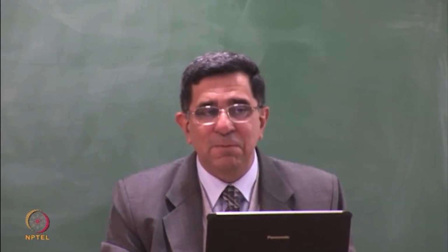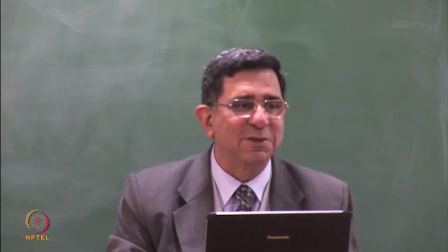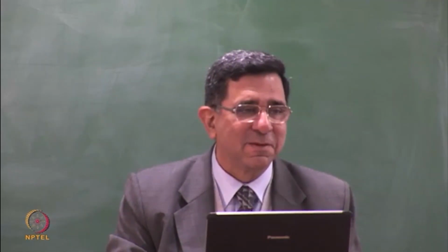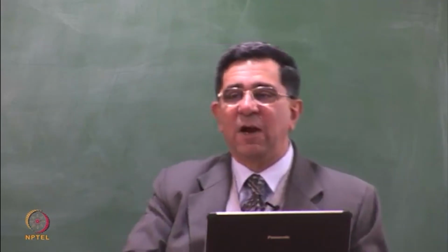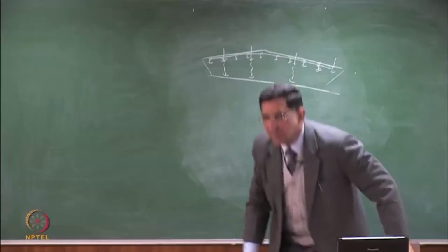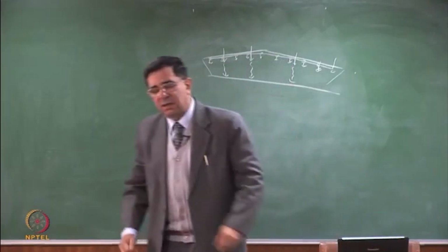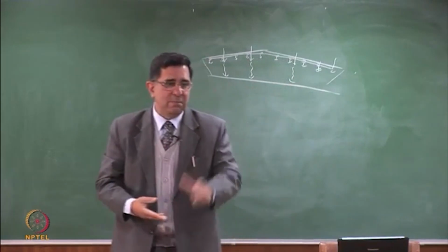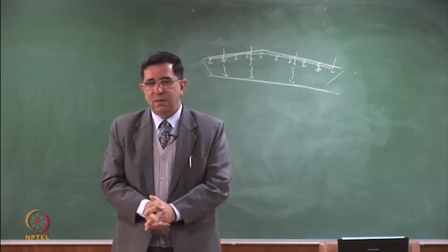Peak precipitation rate, peak leachate rate. So these are the two values that you need for hydraulic design. However, you can do many simulations and come up with the appropriate values. HELP is a good software to do this.